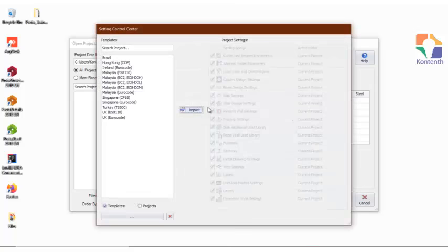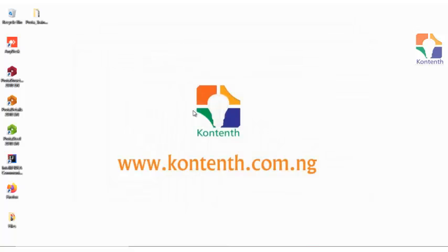And now the next window is where you have all the design codes. You have several design codes here, from Eurocode to BS standard, and you have some other Malaysia code where they use Eurocode 2, Eurocode 8. And for the purpose of our training here, we will be using the UK code, which is BS standard, BS 8110, which I believe everyone has a copy. We already sent out links to download that. If you've not done that, you can do it as soon as possible in order to follow along. So we'll select the code, the standard you wish to use in this project, and then import.